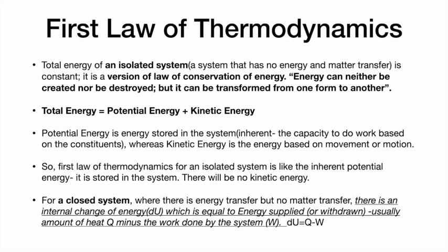And for a closed system, where there is energy transfer but no matter transfer, there is an internal change of energy. The energy transfer can be taken as thermal energy transfer. In this case, there will be an internal change of energy which is equal to the energy supplied or withdrawn, usually the amount of heat, minus the work done by the system.